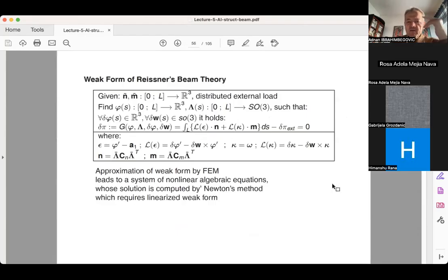I can also do the material representation. So here it's in the conclusion. First, I stated if you do a spatial formulation, here's the way, in the conclusion, the virtual work is written as a Lie derivative of your strain measure, which is written as V prime minus a1, scalar product with the stress resultant of axial and shear forces, and then the Lie derivative of your bending strain measure, which is little omega.